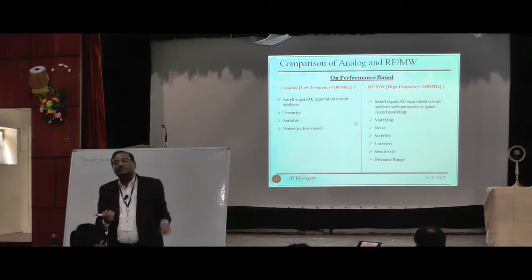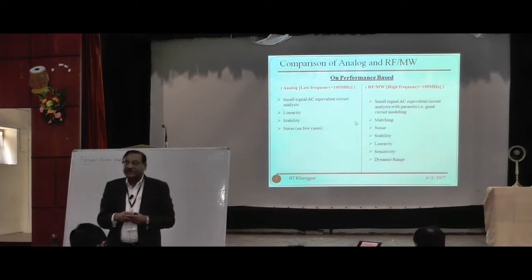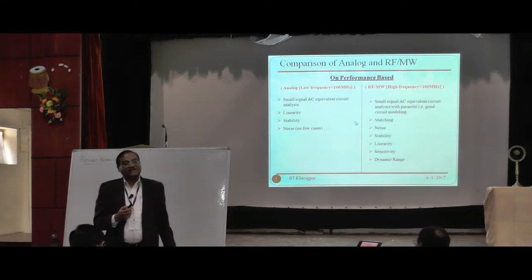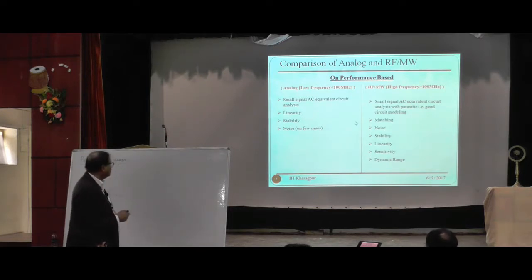In between these two is what is known as the dynamic range of a signal. For any protocol, RF system design, this is defined. The protocol tells what the minimum signal you have to detect is and what the maximum signal you can handle is. So that is the dynamic range.